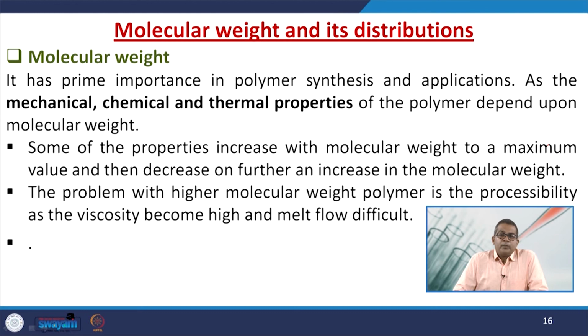Now, a higher molecular weight sometimes may create another problem with respect to processability, because when you are having a bulky structure or a bulky molecular weight, then the processing of that particular polymer would be extremely difficult. So, either formation of a different shape or formation of other things may become difficult.